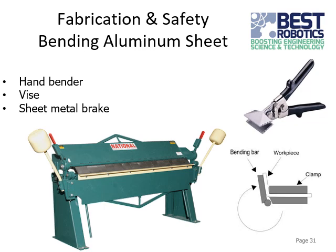Do note that if you do too tight of a bend, if the radius of the bend is too sharp, you can actually break the aluminum. It'll just snap. So it can be helpful to put something like a dowel rod or something rounded on the inside of the bend that you bend around, so that you have a nice gradual curve, and that can keep the metal from breaking.